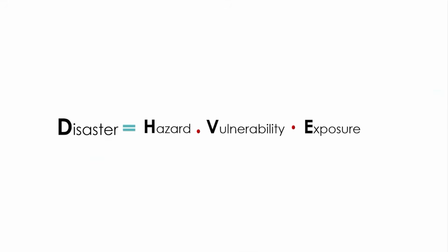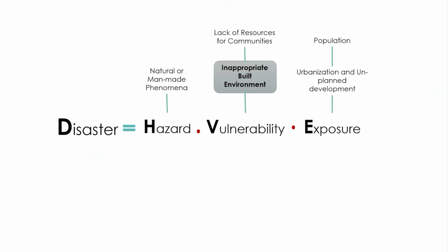That is because of disaster prevention, primarily, because we want to make sure that there's no disaster after an event, maybe an earthquake, maybe a strong wind. Of the disaster components that we have seen before, the most important one is vulnerability, because we can't control the hazard so much. Exposure depends on growth, urban population, planning, and so on. But vulnerability of a structure is entirely the structural engineers' and architects' domain. So if we reduce the vulnerability, we can reduce the disaster risk. That's the intent, and that's why we need to make sure that the structure is actually safe.